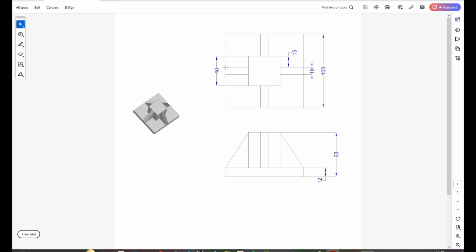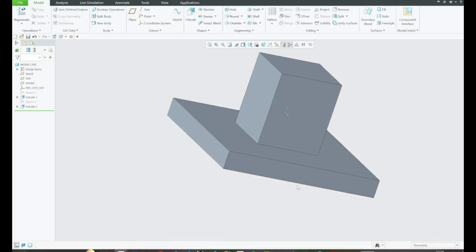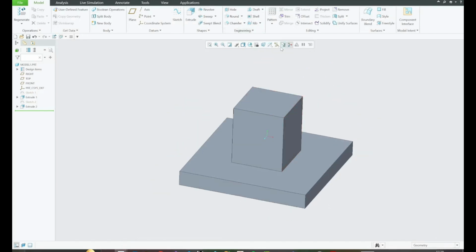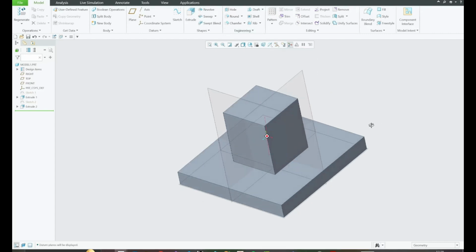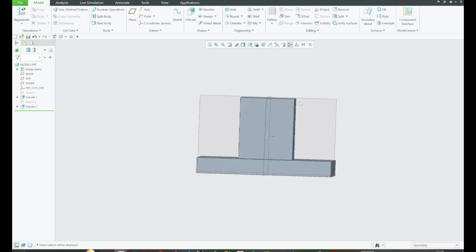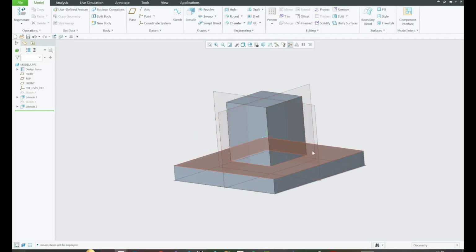Now we've got these 4 ribs that we need to make. For that, we're gonna use the rib command, which is over here. And for that, we need to turn our plane display on, because you'll see in a bit why I did that. So to make the rib, we need to make a profile of the rib, which is going to be used to make the actual rib. We're not going to use trajectory rib anymore. That's going to be in one of our future videos. But in this case, we're going to make a profile rib.